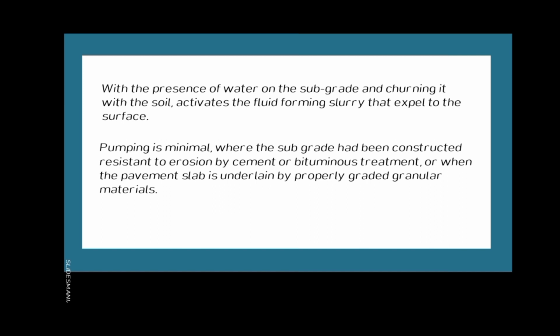So with the presence of water, guys, the water passes through the side of the cement and the soil, and forms a semi-liquid mixture, which is what spurts out. Pumping is minimal where the subgrade has been constructed resistant to erosion by cement or bituminous treatment, or when the pavement slab is underlain by properly graded granular materials.